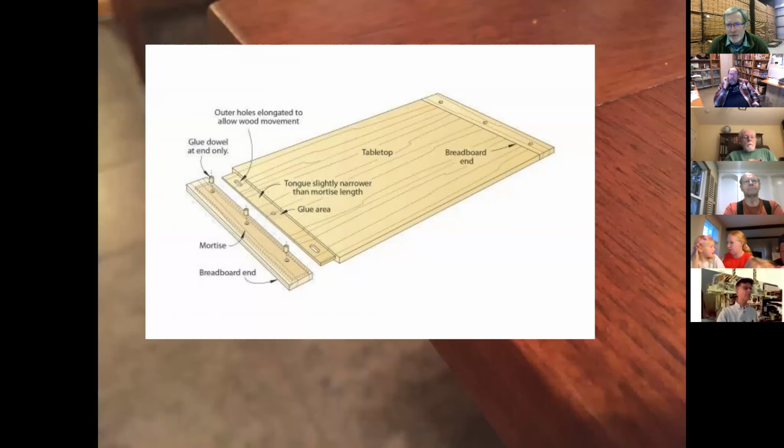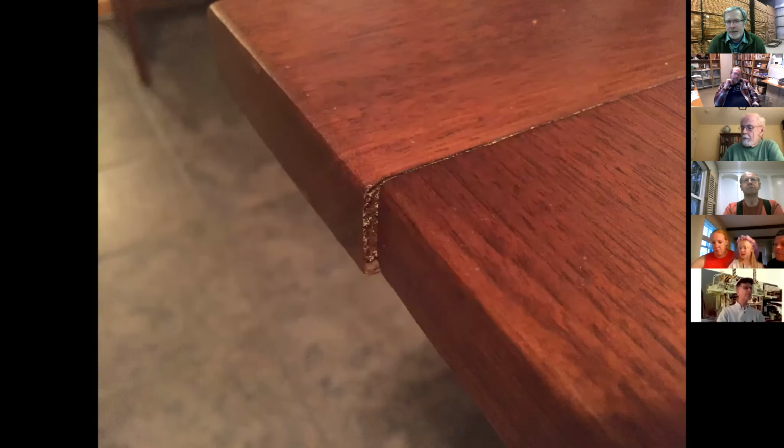For normal wood, it's not too hard to predict these things if we have a uniform plane of reference. So let me give a classic example of seeing some of this. A beadboard tabletop is a classic example of seeing moisture changes in a piece of woodwork, right? We know that typically in the wintertime, we'll see the width of the table shrink. And why is that?